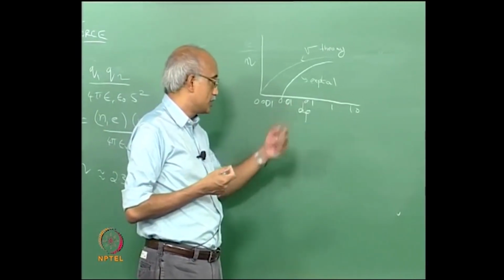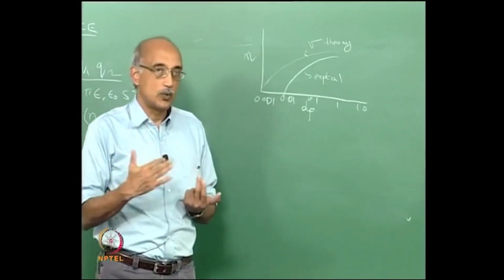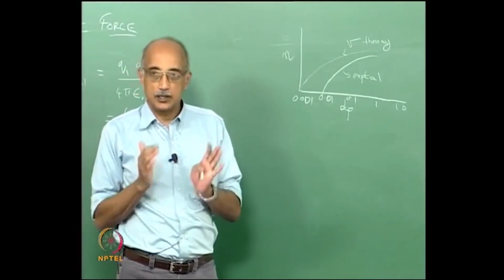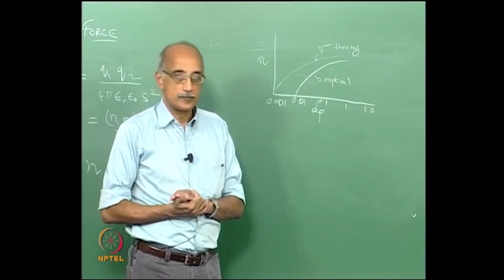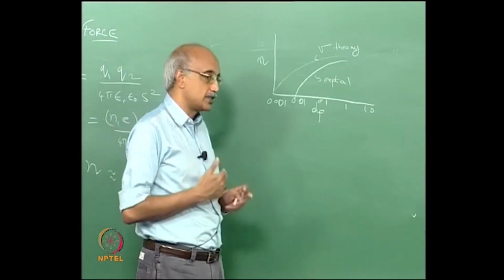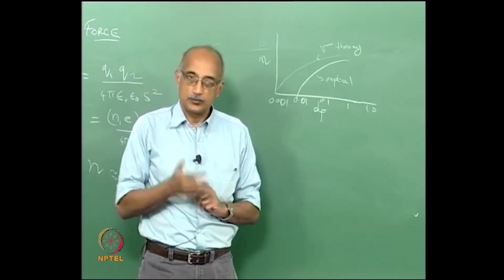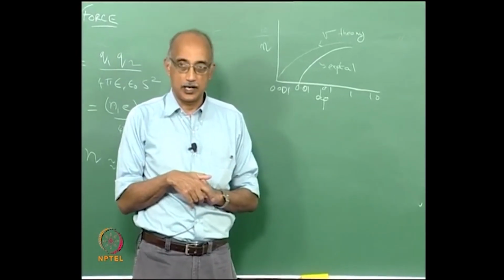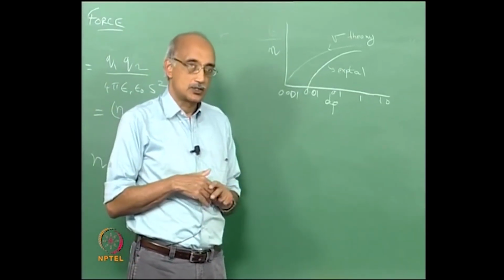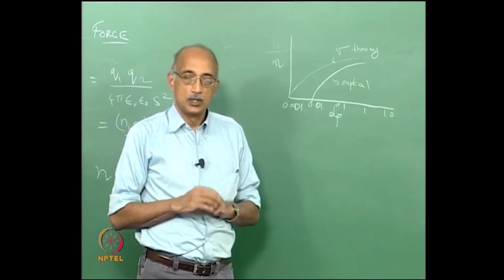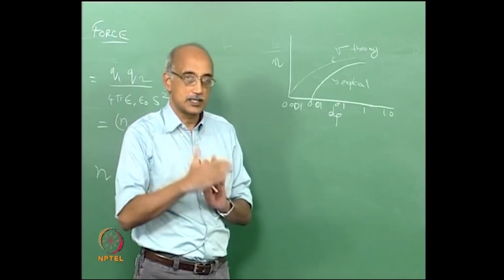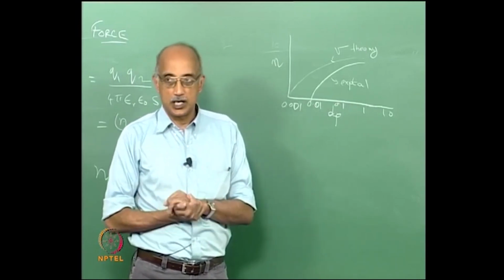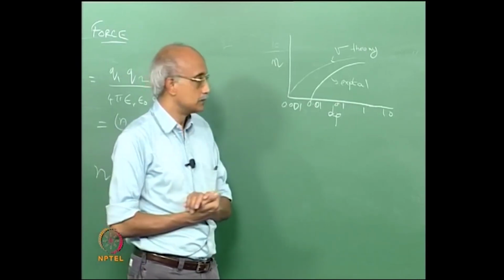As you approach the 0.01 to 1 micron range, electrostatic effects become comparable to diffusive effects. As you exceed sizes of 1 micron, the diffusion drops quite rapidly, while electrostatic effects drop less rapidly. So electrostatic phenomena continue to play a role beyond a size where diffusion stops being an important phenomenon.